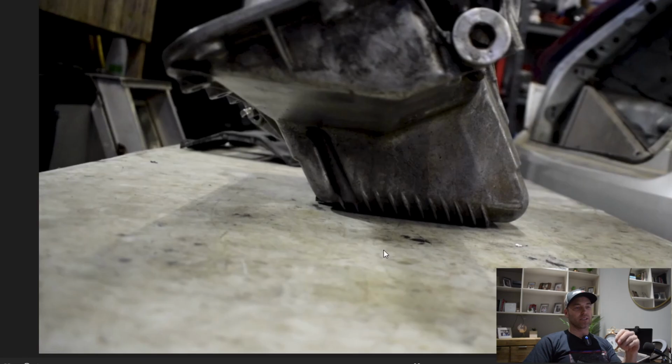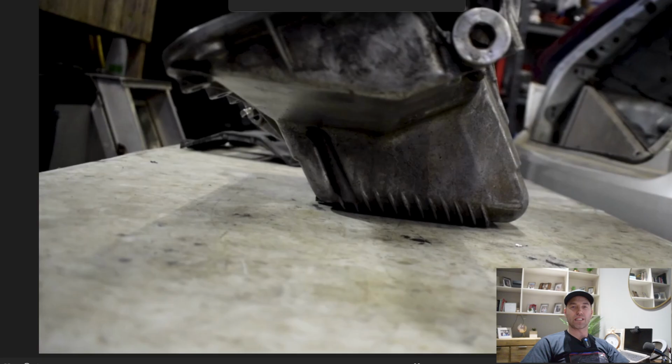If you look at this picture of the sump, you will see, okay, it's sitting a bit skew, but as I mentioned before, there isn't a lot of volume within this sump, especially because a lot of the oil actually sits at this level, right? But in a race situation, you can't have the oil level up here because you can't box it up here. So we need to add volume at the bottom to be able to still keep the 5 liters, but drop the oil level down so that we can box the top here. Does that make sense? Let me create a crude sketch for you.